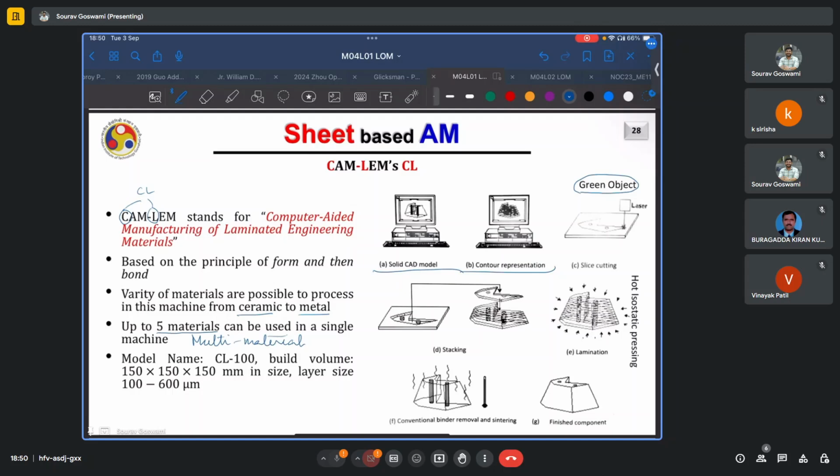The next step is stacking. So here we see that in each layer, you have these two holes which actually act as the reference along which these parts from each successive layer can be stacked. Say you have these two rods or two bolts and they act as a reference. So each hole is aligned with these bolts or rods, and then they are just placed on top so that you have perfect alignment or precise stacking.